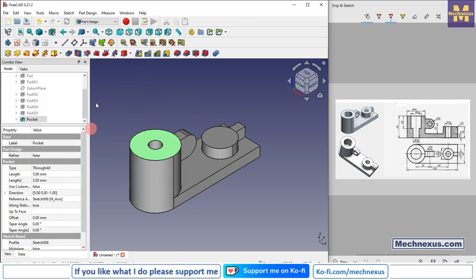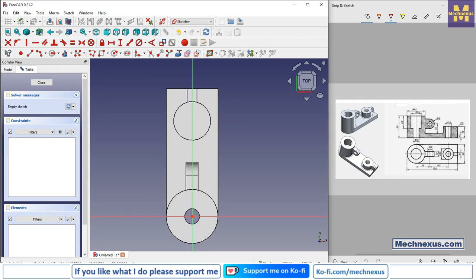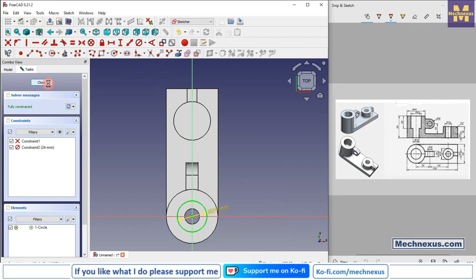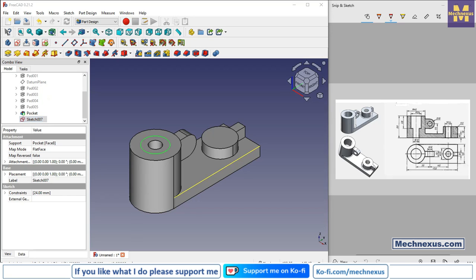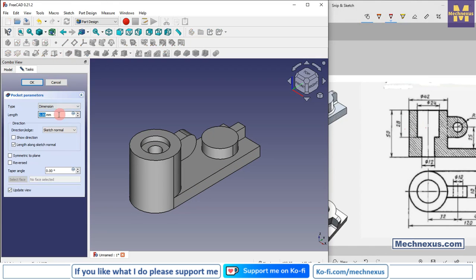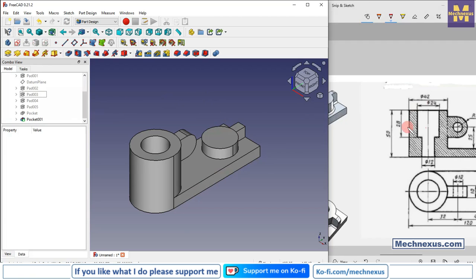Now I will select the top face and click on the sketch, and I will create a circle of diameter 24. Select the circle and select diameter, provide 24, click on close, and this is of depth 28 mm. So create a cut and provide depth 28 mm.